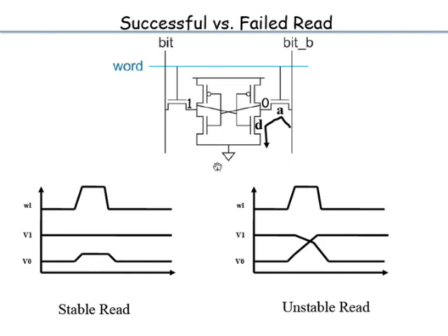When you read the cell, there has to be determinism. You basically need to know what happens to the cell content. We'll see when we study DRAMs, when you read the cell, you destroy the cell content. But it always happens, so you know, and you deal with it in the circuit design. You'll see how that is dealt with. You cannot have this random destruction or flipping of bits. So an unstable cell can lead to this kind of a problem.